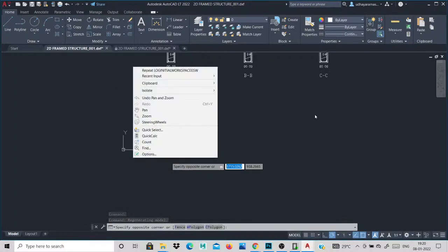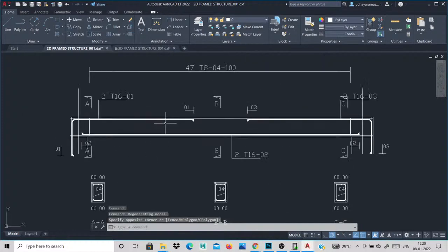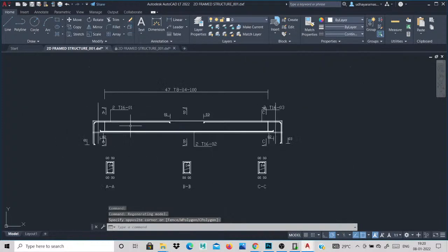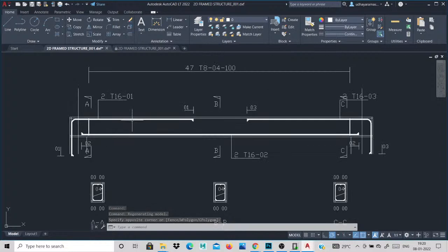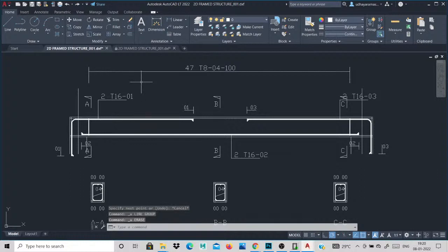See, automatically it's visible. This is our cross section and longitudinal section for your beam. This is a top zone. This is a bottom zone and all the zones also. You can edit or change anything for this reinforcement also. This automatically goes to extra line. If I need extra reinforcement and all the things, you can edit this detailing also in this CAD. See, this is our reinforcement detailing for this beam.